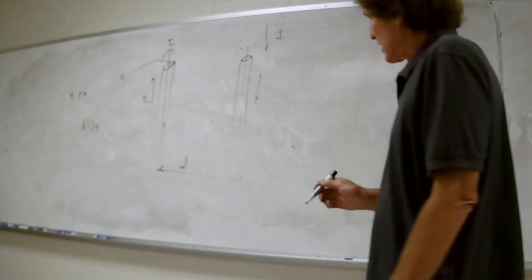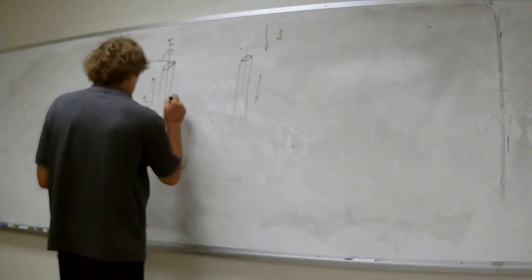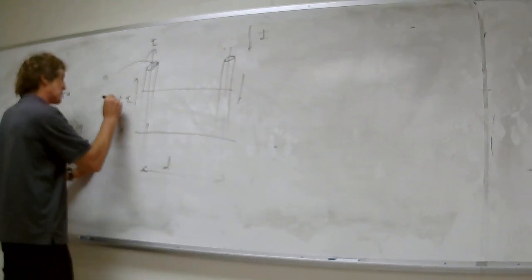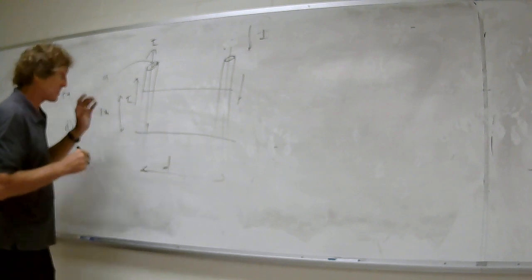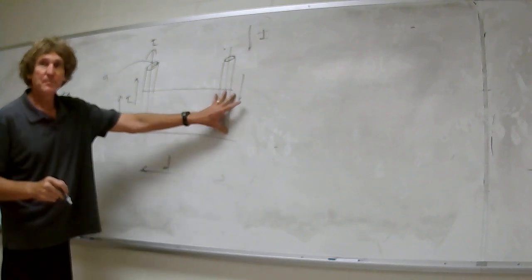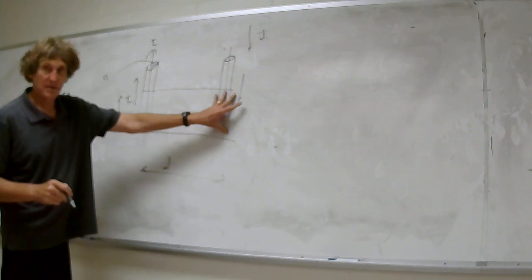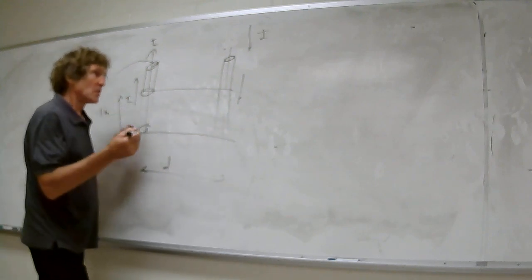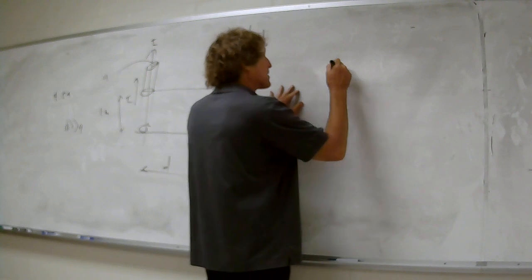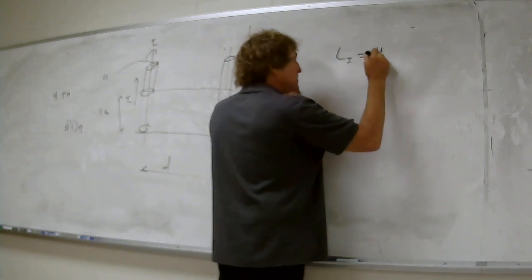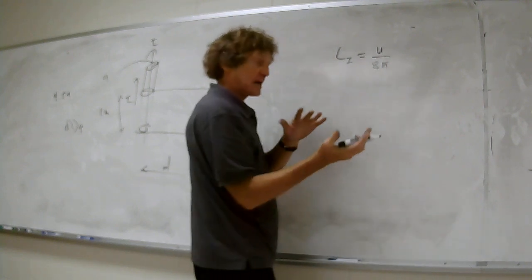Now, if we look at a per meter, you better do it per meter. All right, we're going to take 1 meter here. This is the length, and we want the inductance in that. Well, we've got the inductance of the wire, don't we? The internal inductance we calculate. Do you remember that? The internal inductance of a wire is mu over 8 pi times the length.